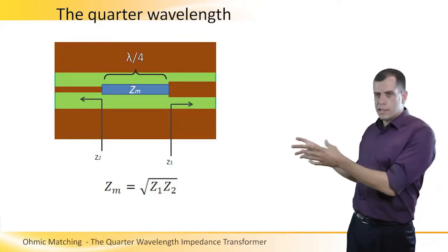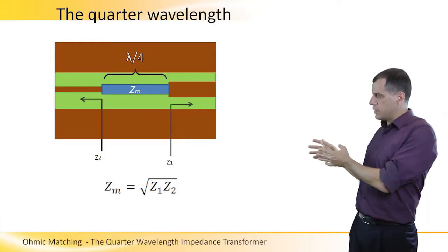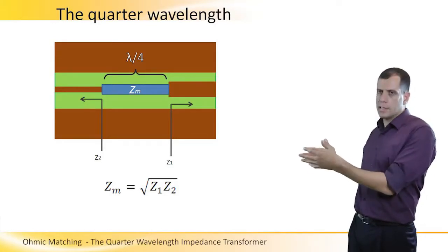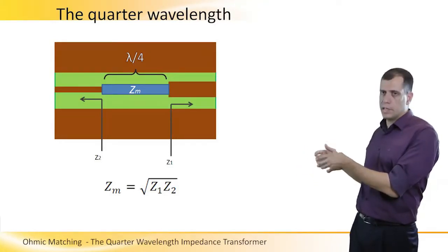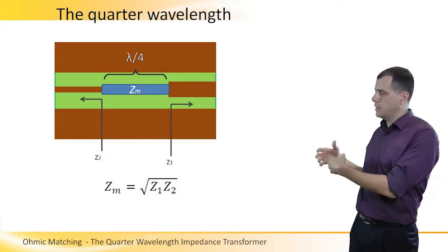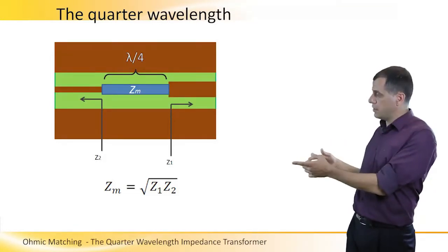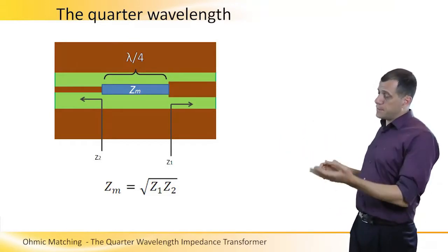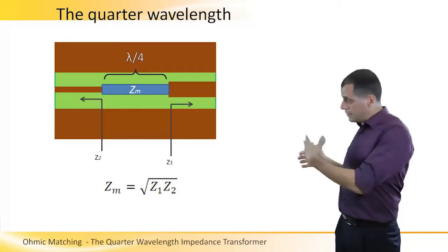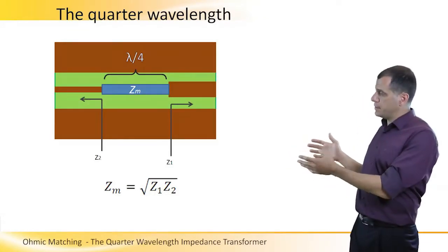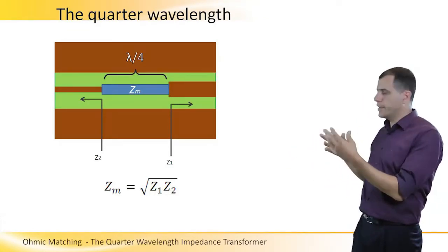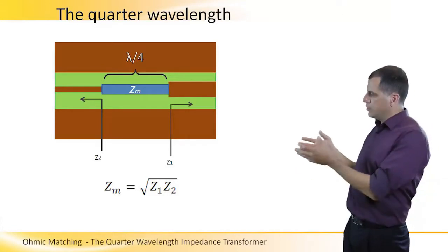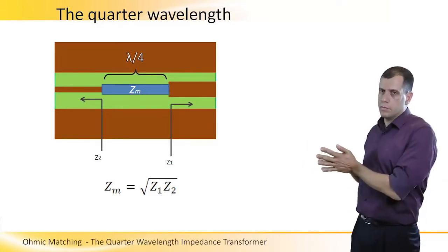The transmission line that reaches this device also has an impedance of Z1 in order to maintain a good return loss, good matching to this device, on the right hand of this PCB. On the left side of the PCB, there is a connector or device which has an impedance of Z2.